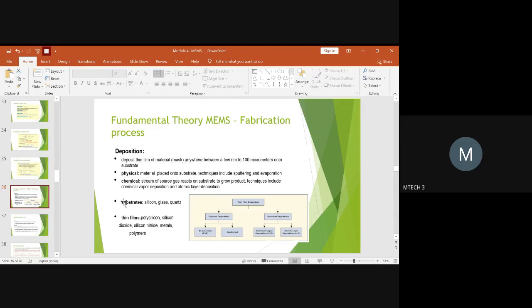The most common substrates used could be silicon, glass, or quartz. Quartz is a common type of piezo material which is available in nature. And glass is a very inexpensive and cheaply available substrate, right? Usually when you want a good amount of adhesion of the thin film, you need to opt for a better substrate. For that, silicon is the most feasible one. But if the materials are ceramics and you subject them to to-and-fro motion, like in a cantilever, you should have good adhesion.